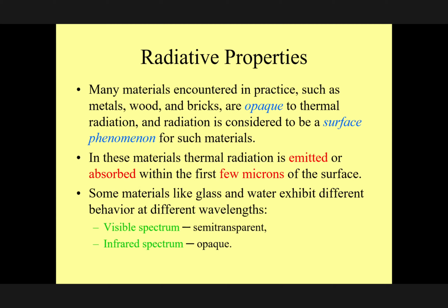But when we are talking about a gas, again, it depends on what concentration we're talking about. If I'm talking about the environment, I can assume it is transparent, and radiation passes through. But when I'm trying to design a furnace where I'm dealing with a lot of smoke, I cannot assume it is transparent. Some of the radiation coming from the fire will be absorbed by the gas, okay? Therefore, depending on the application, we have to keep in mind what the characteristics are.